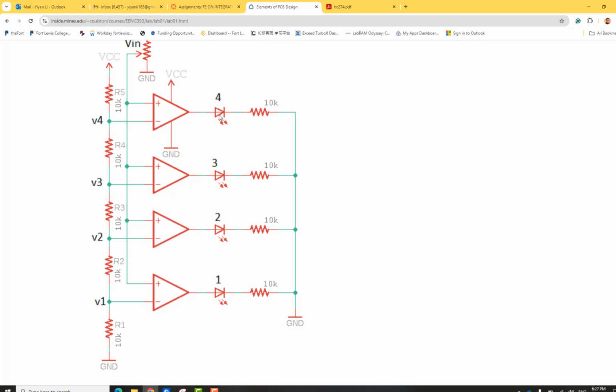So you guys are familiar with LEDs, right? An LED has an anode and a cathode, it's a PN junction, so current only flows in one direction. And this is 10K. I've never used anything more than 1K for LEDs. So probably it's trying to dim it anyway. Usually I use 300 to 1K. Anything larger than 1K will dim it significantly. But 10K, I don't know, try it. If it doesn't work, you can switch to a lower resistance.